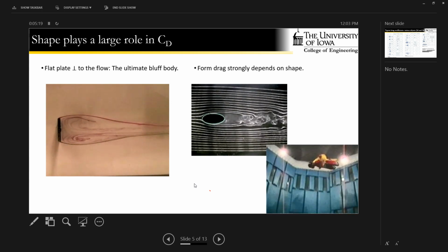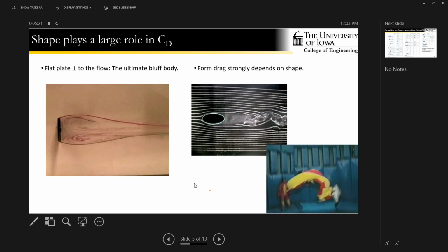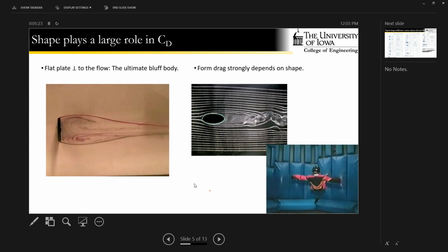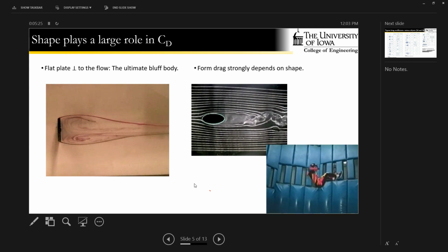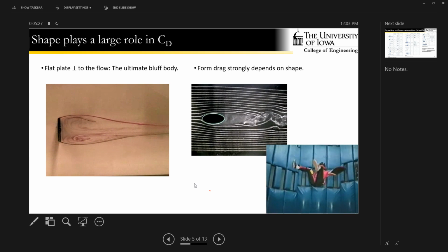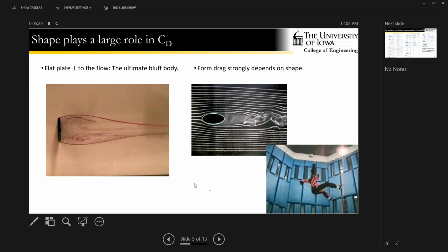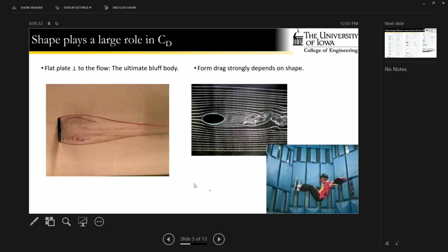What you can see is that very clearly defined flow separation occurring behind it. In fact, if you were to try to calculate the shear stresses on this and figure out how much of that drag was made up of frictional drag and how much of pressure drag, what you would find is, in order for frictional drag to be developed, there has to be some flow creating shear stresses that are in the direction of the flow, right?